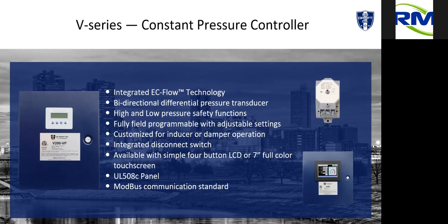There's not one setting in this controller that you cannot adjust in the field, so that we can truly customize it for your application. We also have several different programs, meaning that my fan program does not run my damper. I have a fan program, a damper program, and a combustion air program, which we can talk about in another seminar, but each program is built for that application.